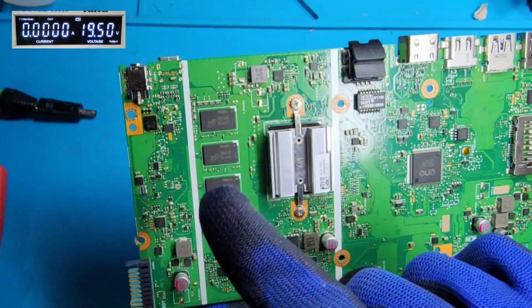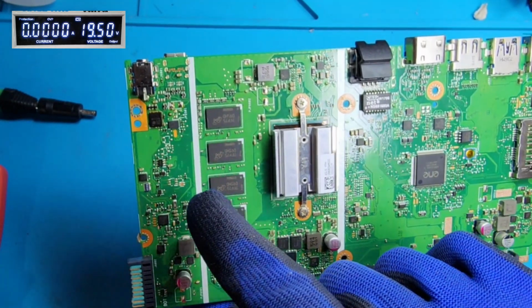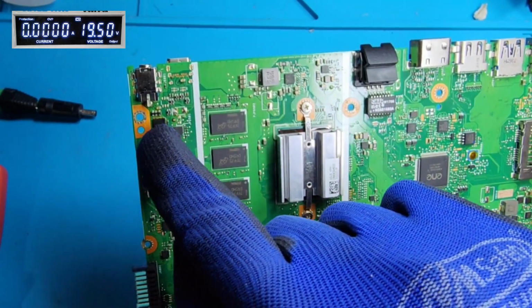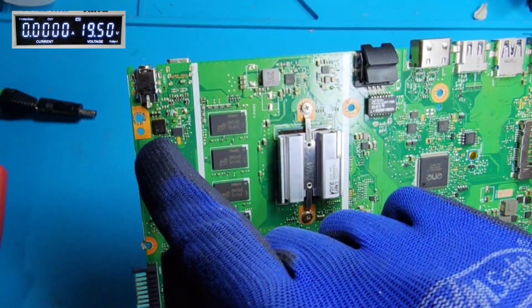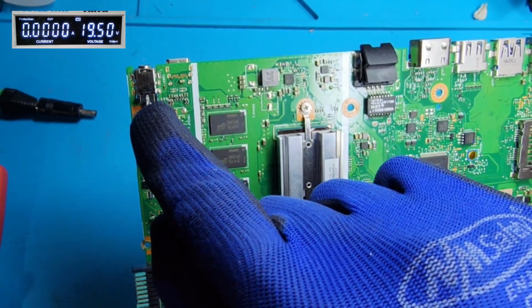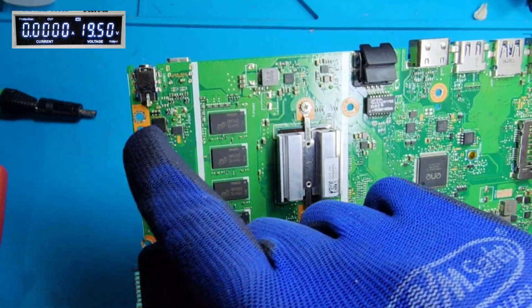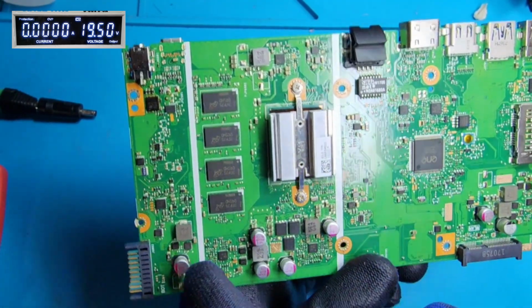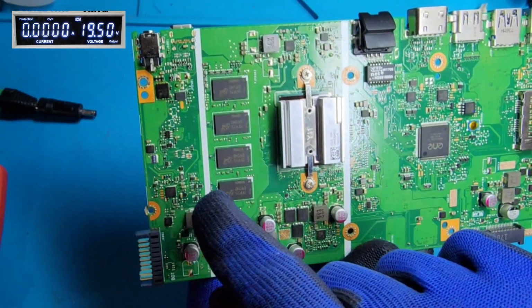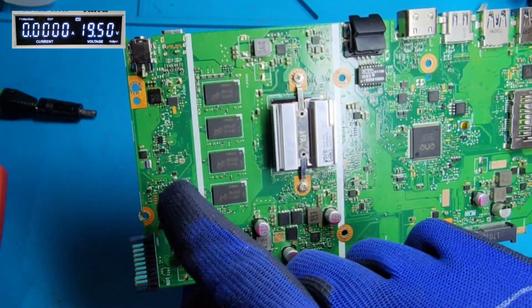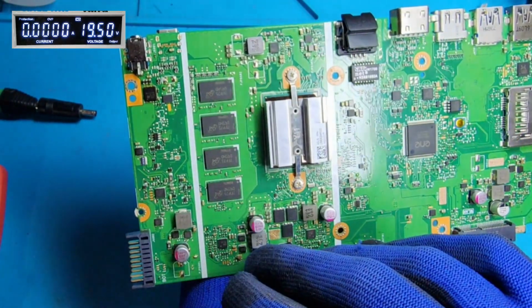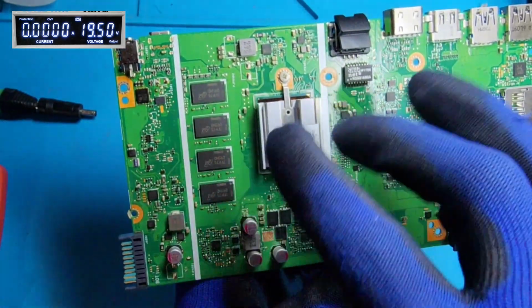So I have seen many of the laptops which I received for repair that have this MOSFET taken off the motherboard and shorted with a jumper wire from its source to drain. So there's no control for this MOSFET. If there's no control, the voltage will always be present if you connect the adapter. So the charger IC's responsibility will be cut off, and there is nothing to protect your motherboard here.